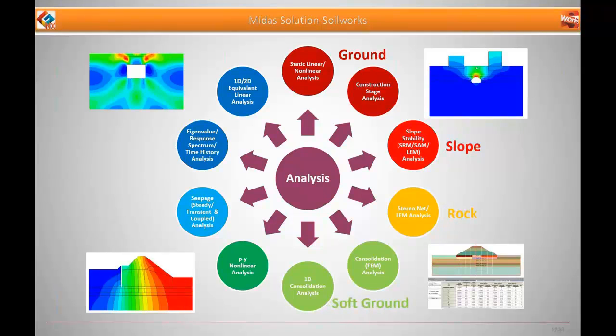In the soft ground module, you could consider both the traditional 1D consolidation analysis as well as finite element analysis. In foundation, you could perform PY nonlinear analysis. In seepage, you could consider both steady state and transient state, and also the coupled analysis, which I will talk about in detail. And finally, in dynamic, you could perform eigenvalue, response spectrum as well as time history analysis, and also consider 1D and 2D equivalent linear analysis.